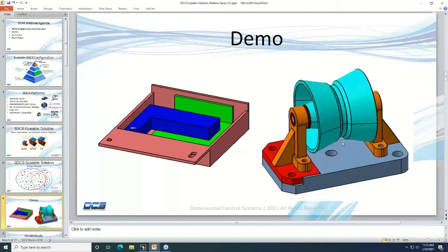The right model here is the pulley model. That's the model we're going to be extracting joints and constraints from. So this is still used in DVM. We're going to be pulling the CATIA constraints out of CATIA and into our 3DCS model, and we're going to automatically create moves from that. And then same with the measures and GD&T and CATIA. We're going to pull that straight out into our model.